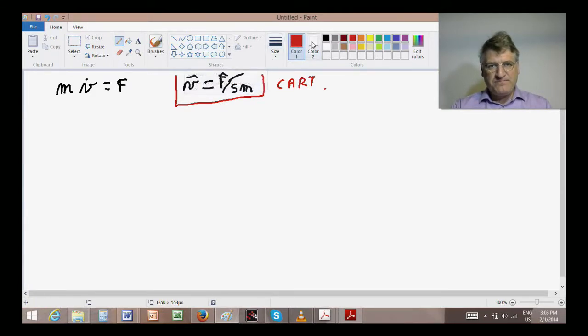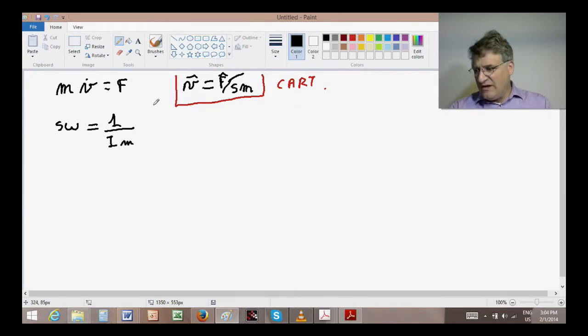Now for the motor, we have these two differential equations, one in omega dot and one in I. The first equation in the Laplace domain becomes S times omega is equal to 1 over Im times Kb times I. Again, I skip the hats for notational convenience.